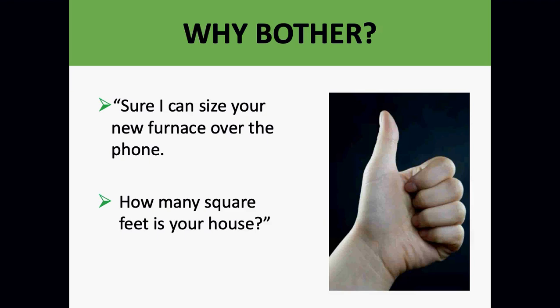They used to say, close enough was good enough. These old rules of thumb are going to get you in a lot of trouble with building officials. It used to be they'd say so many square feet is 1 ton of cooling. I've heard different contractors use 400 square feet as 1 ton of cooling, and another contractor use 1,200 square feet. They used to use any number in between. I called it the stand at the curb and guess method. They'd also say 1 square foot requires 30 BTU per hour of heating. Again, that was a standard that they used for many, many years.